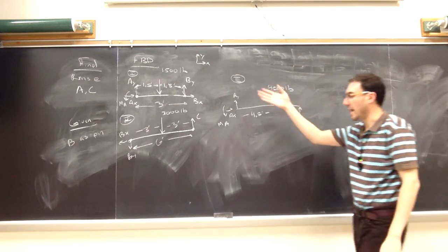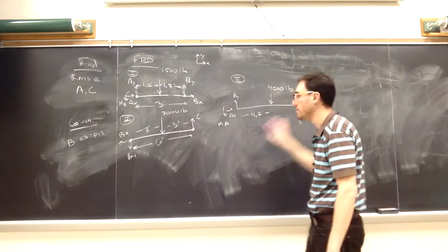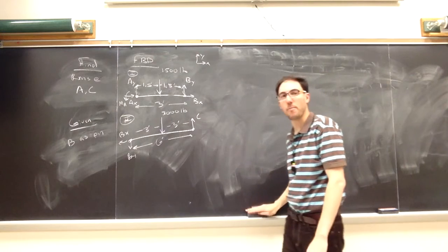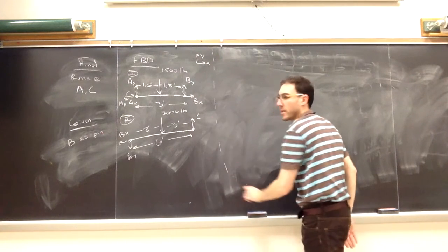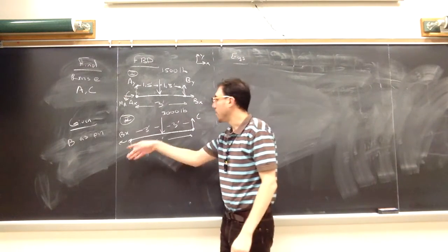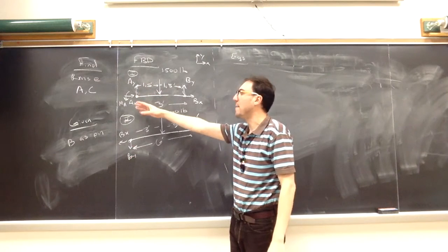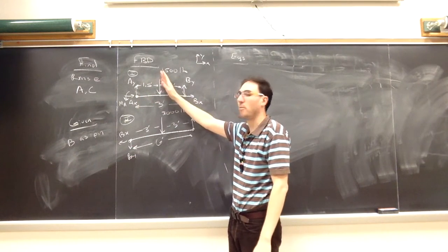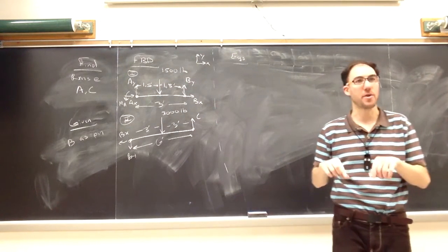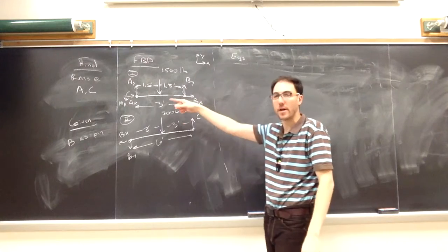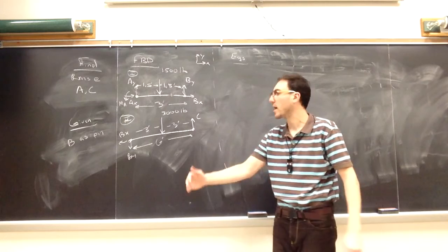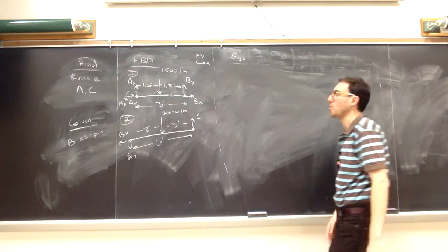At this point, because I have these simplified free body diagrams, it looks now just like something we saw in the frames and machines because we replaced those distributed loads with point loads. And I'll reiterate, externally, the values we get for C, AX, AY, MA are unaffected whether we simplify it to a point load or try to do it as a distributed load. Internally, though, there is a difference, so these pictures would not be good if we wanted to know what the force in the actual material itself was. But we'll talk about that at the end of this course.